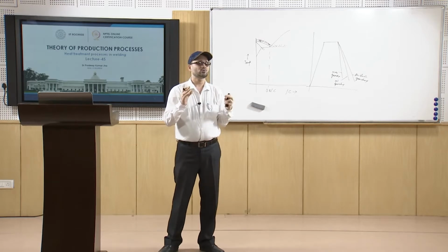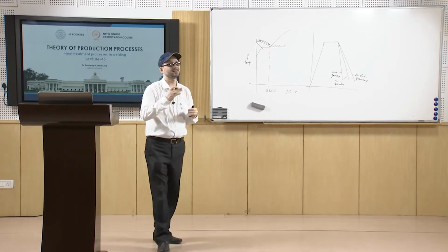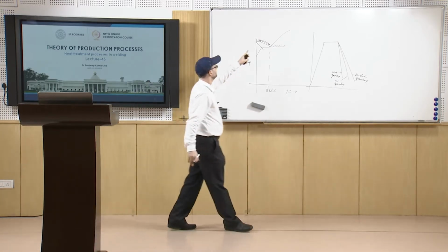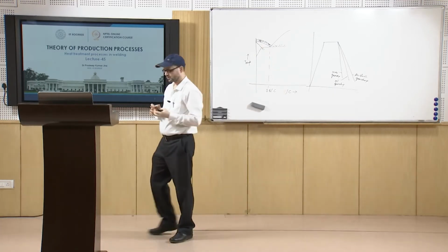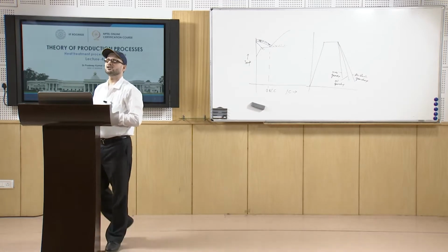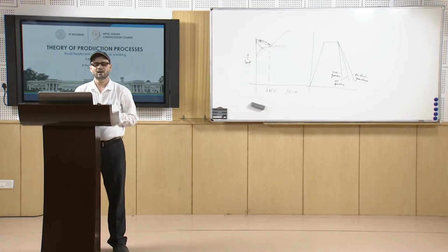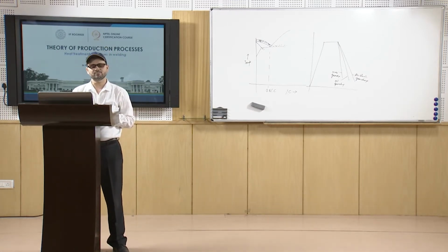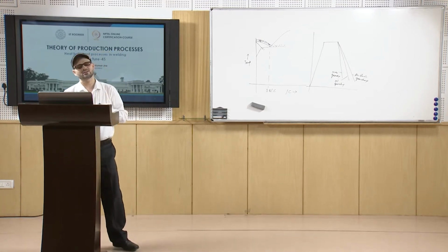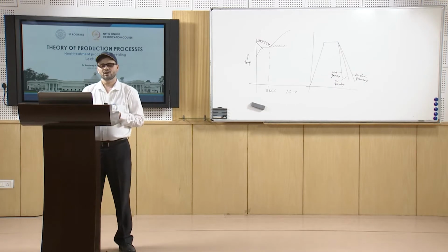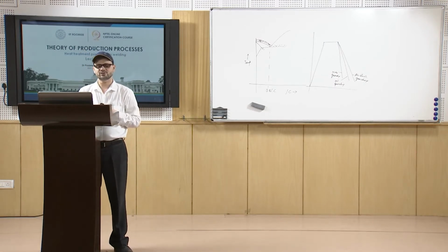Its effect is seen from this range to this range. Quench hardening is seen to be more effective, and up to about 0.6% carbon, the hardness of the steel increases.